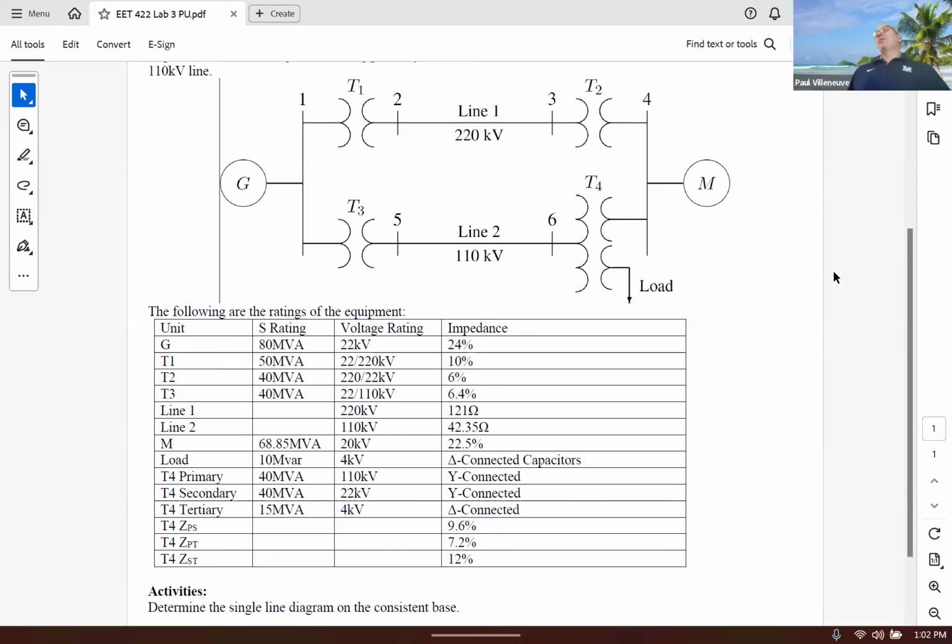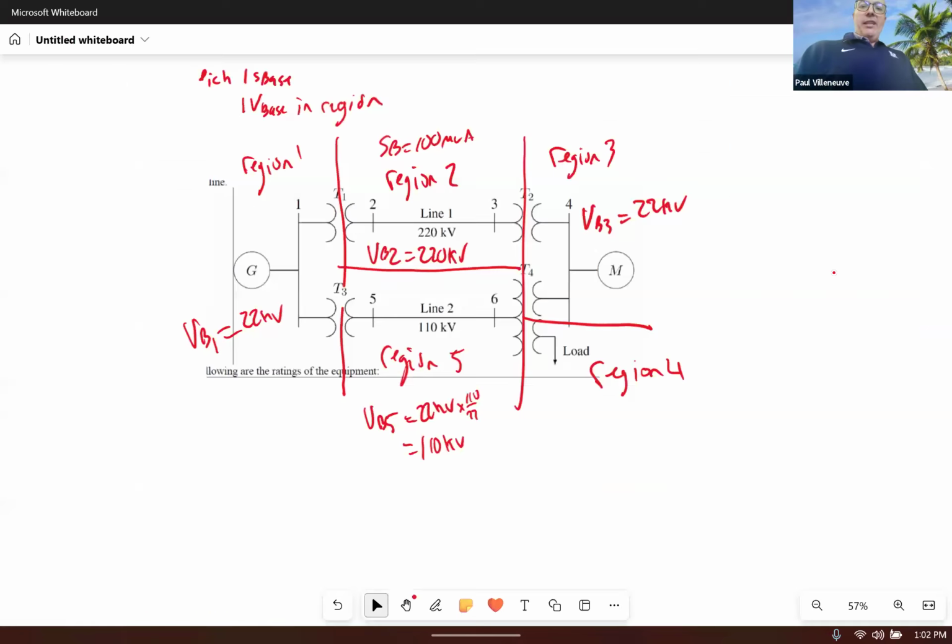Now, you'll notice with a 3-winding transformer, it's got a primary, secondary, and tertiary winding. The primary winding, we'll say it's over here, because we're going from the power side to the load side, right? This is a motor. So that's a load. We'll call that the secondary. And then this we'll call the tertiary or the third winding. Most of the time, if you have a tertiary winding, unless it's exactly the same as a secondary winding, it tends to be a lower power winding.